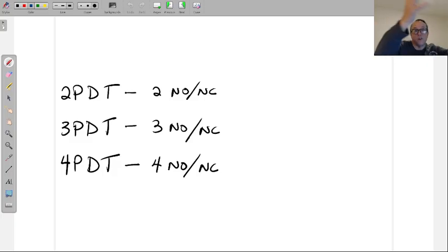Yesterday I showed you that you could also put contacts behind push buttons. Right? You can put 2 of them, an open one, a closed one. I told you you can even stack on top of those to add more contacts to the control circuits for extra things.